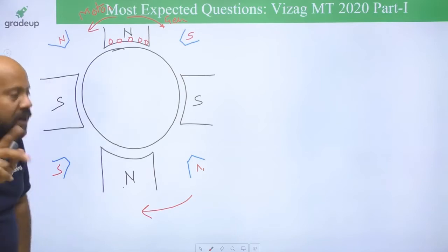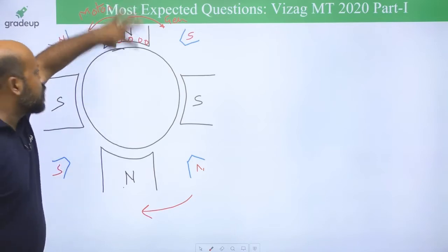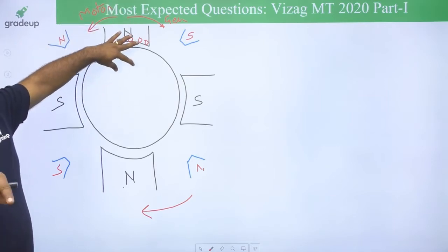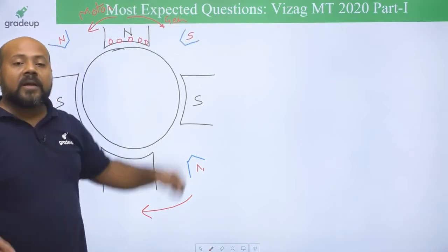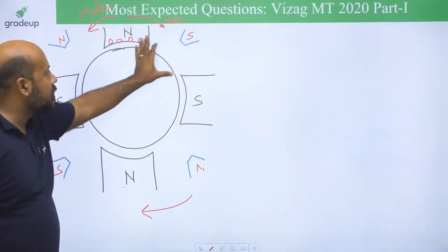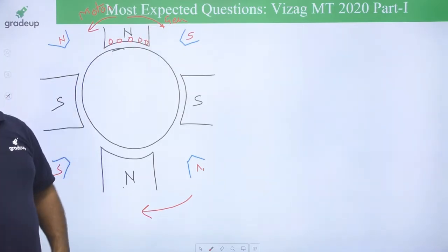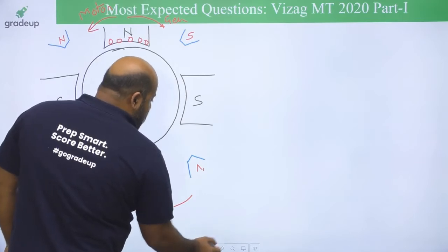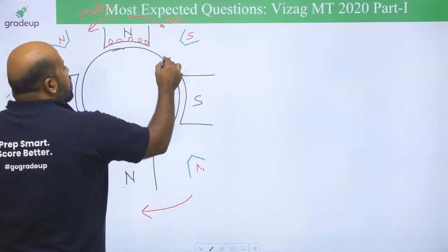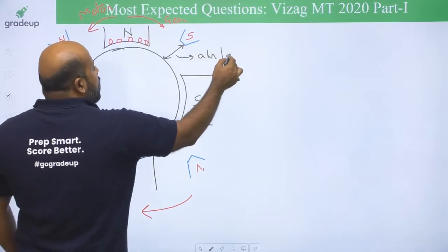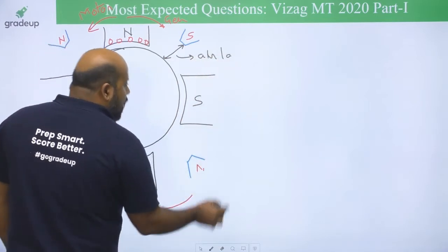The responsibility of the compensating winding is to neutralize the cross magnetizing effect in the polar region, whereas the interpoles neutralize it in the interpolar region. One important difference between the main poles and the interpoles is that their air gap is long. Air gap is large.